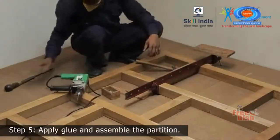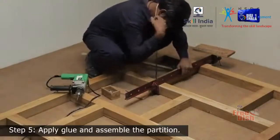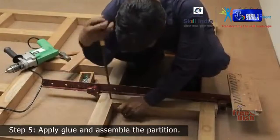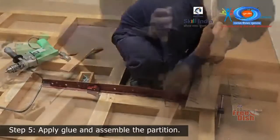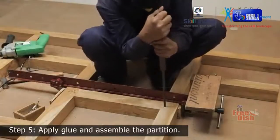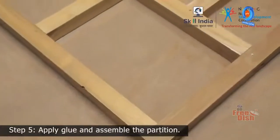Fix the screws and tighten it with a screwdriver. Do it on all the joints. Now you are done with your partition frame.